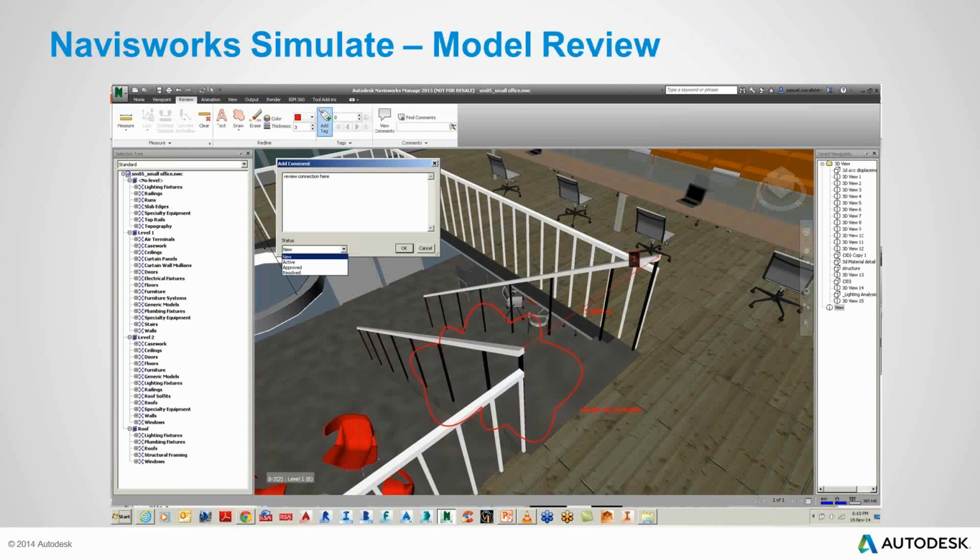And for maybe the non-Revit user in your company, maybe they still want to get inside the model and do their markups instead of you having to print it out. They go and red pen mark it up, then they scan it, and you bring it all back. You can do this inside Navisworks. So they can open up the Revit model in Navisworks, and they can walk through the model intuitively. They can read all the family parameters in here, and they can go and add comments. So they can do a little point revision cloud markup.